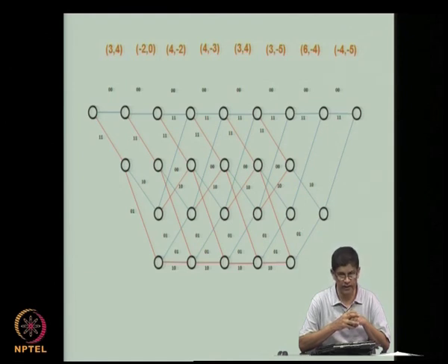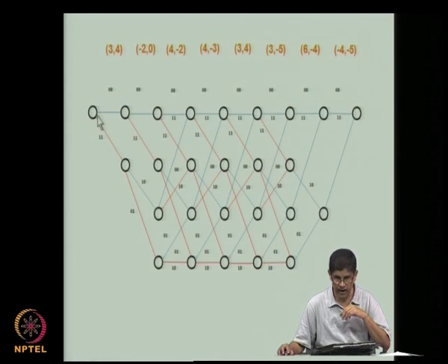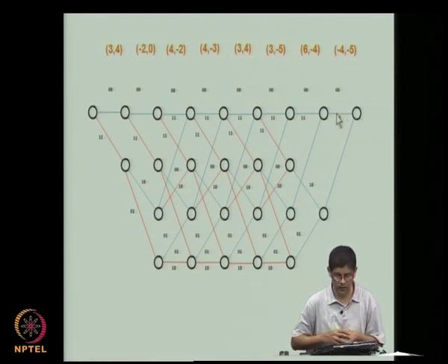Okay. So, we are looking at decoding code words whose branch length on the trellis is 8. That corresponds to 8 message symbols and 16 output symbols. However, you must keep in mind that this is a terminated trellis, because here we start the trellis in the all 0 state, but then we bring it back to the all 0 state. So, the last two message symbols are 0 and thus do not contain information.